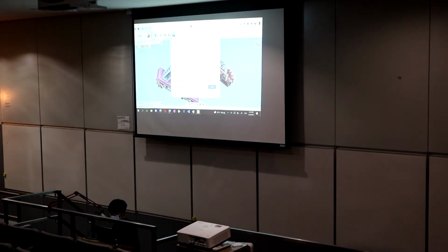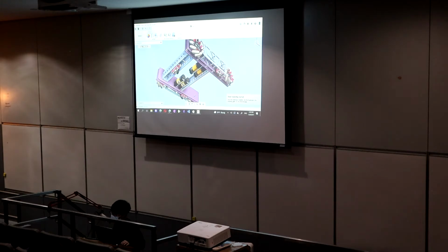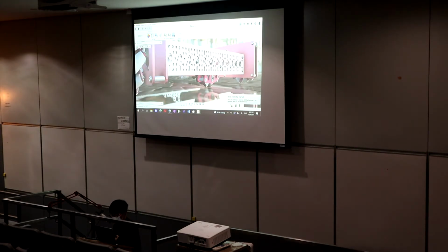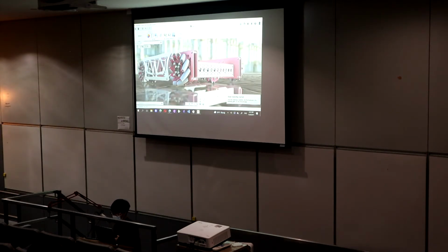Again, we want to do a custom setting where we can define the pixel count, and we're going to do a cloud render. And this will take anything from like 3 to 10 minutes, depending on your internet and how big your image actually is. We can do a back view like that too. Oh, there's a whole bunch of stuff I didn't set appearances to. But we can actually revisit that process.